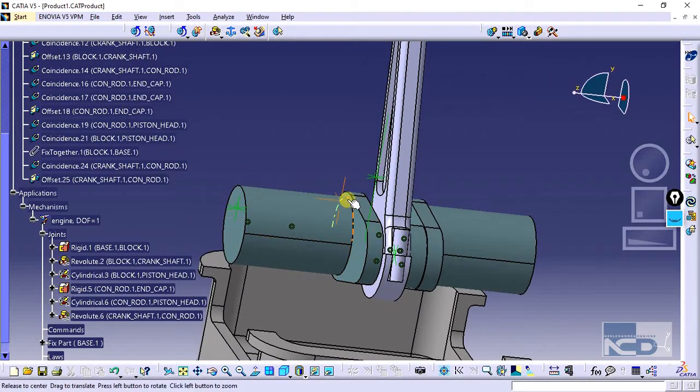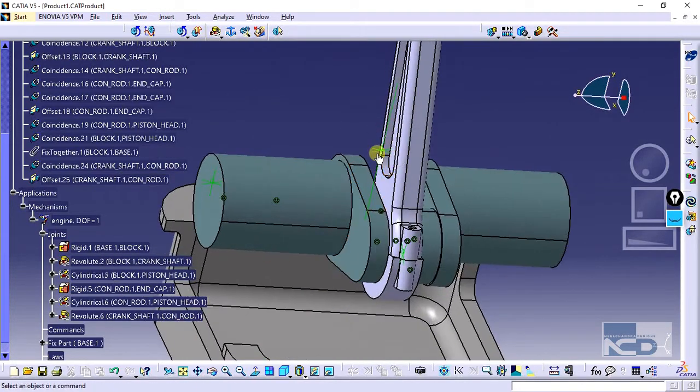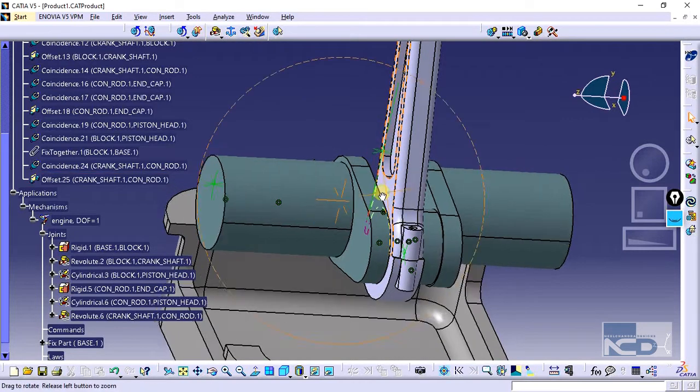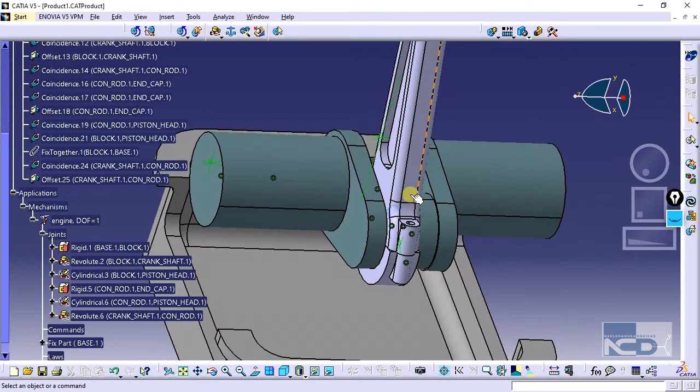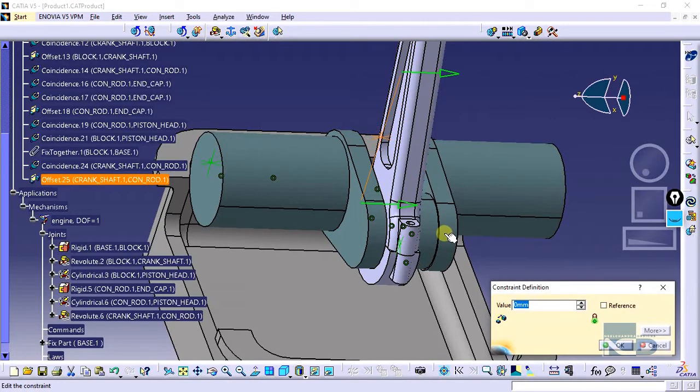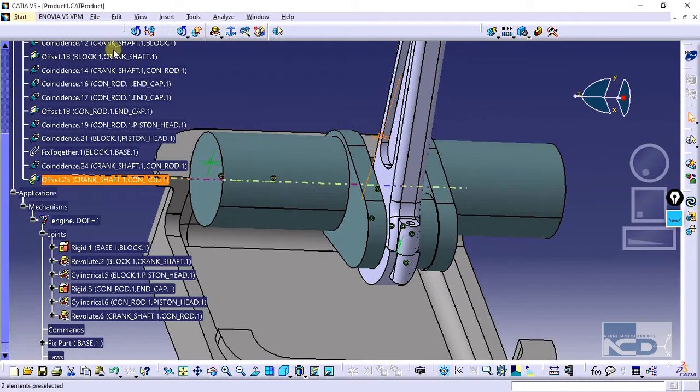And one mistake over here is that we have created a revolute joint between these two sections. So it has just stuck it over here. You can find that the space between them is lost. So I can just double click over the 0 again, and I can just put a new space. That doesn't matter. And you can just update your project. This is the update.